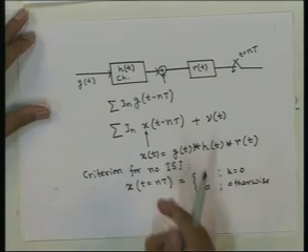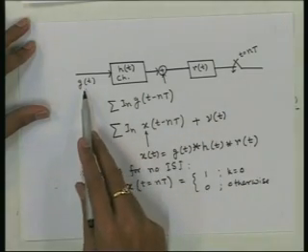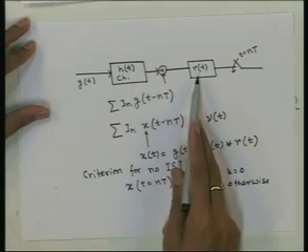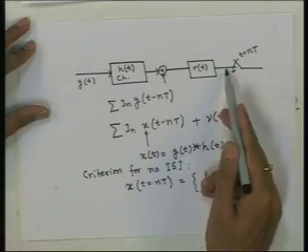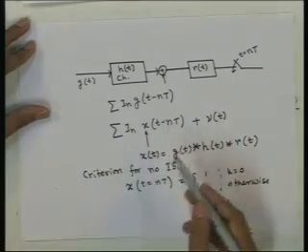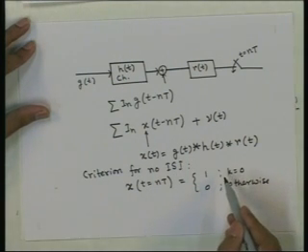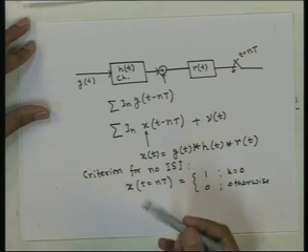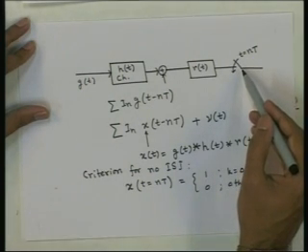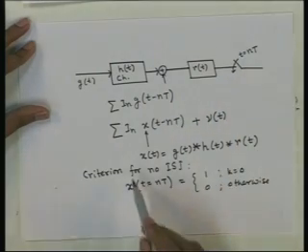The x(t) is the pulse resulting from g(t), h(t) and r(t), and after g(t) goes through all these filters it becomes x(t) here, and x(t) should have 0 values at the multiples of T seconds except at the 0 itself, because at t equal to capital T the next sample is taken here and that sample should be contributed by only the next symbol.